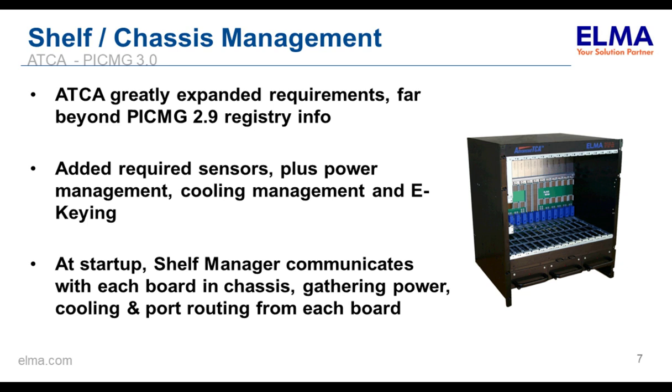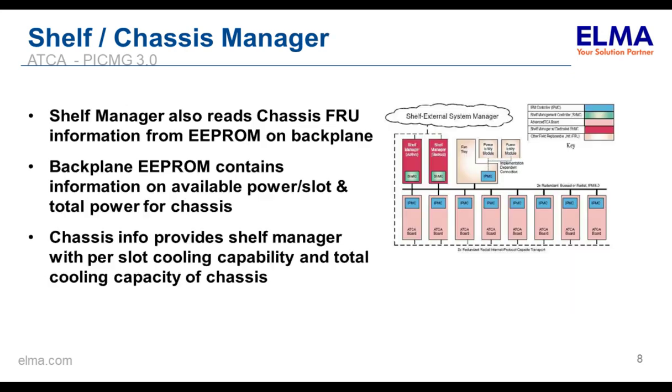So when an ATCA system first starts up, the chassis manager communicates across the IPMB to every board in the system, gathering power requirement information from each board, cooling information from each board, as well as port routing information or requirements for each of the boards.